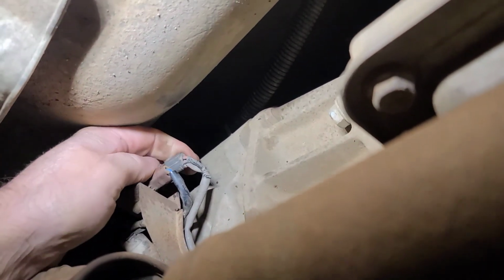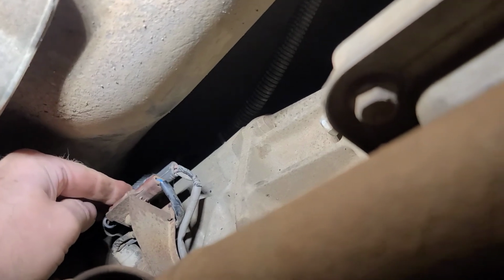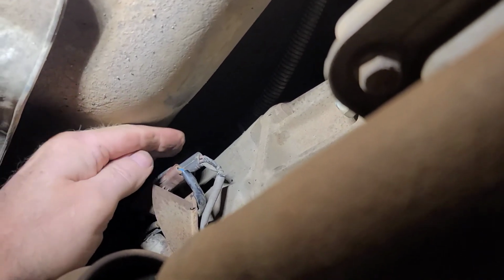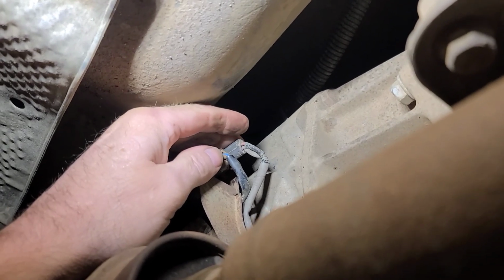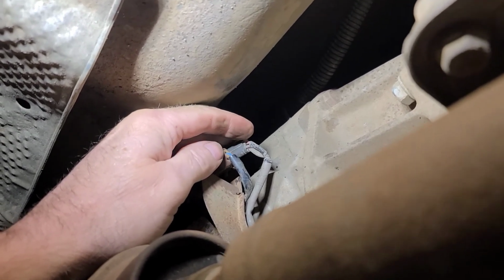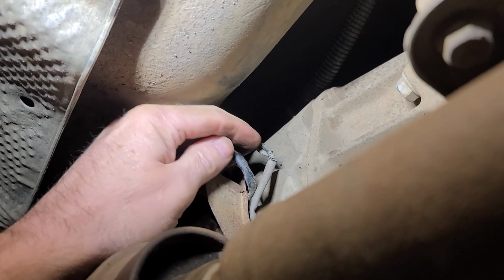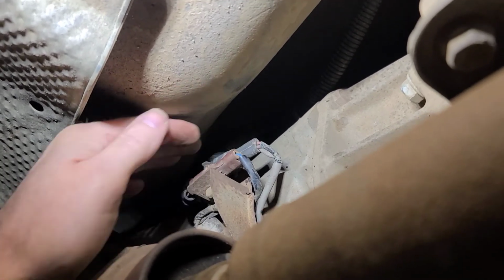So there's the used switch installed. The gray connector is the upper one, and that is for the two-wheel drive, four-wheel drive switch. One of these wires will be 12 volts with the key on from the actual transfer case controller. The other wire is ground. So if you backpin the 12 volt wire, when the transfer case switches to four-wheel drive, it should go to 0. And it wasn't doing that. So again, we're going to try it now.